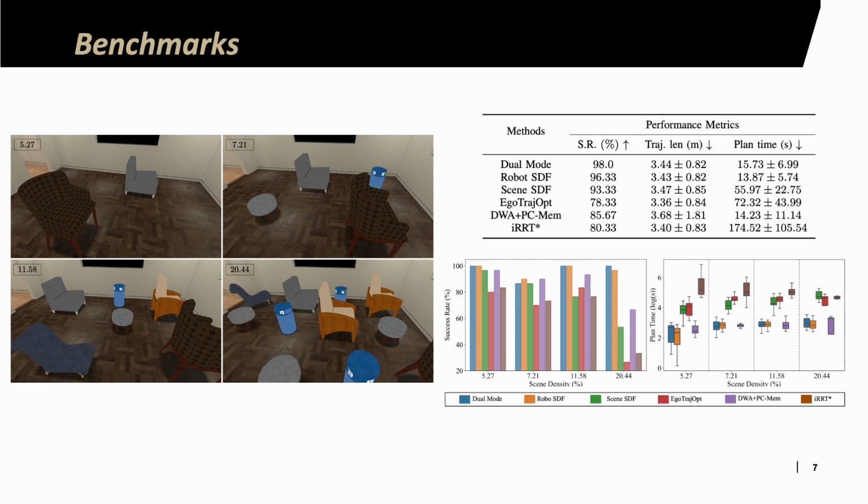DWA is fast as it only considers the robot's locality while planning, but its evaluation function is known to be sensitive to dynamic obstacles. Our method avoids these issues and gives the highest success rate with a competitive planning time.